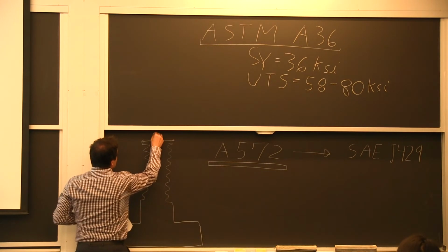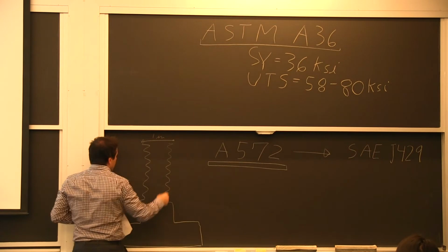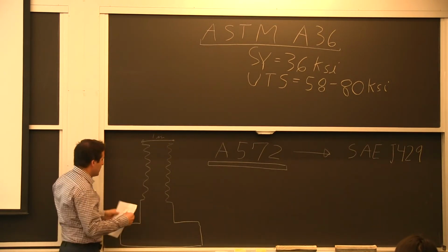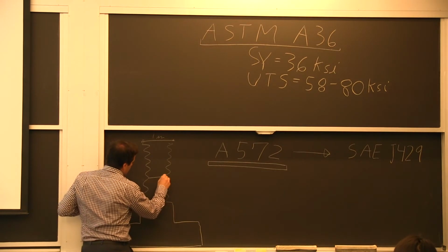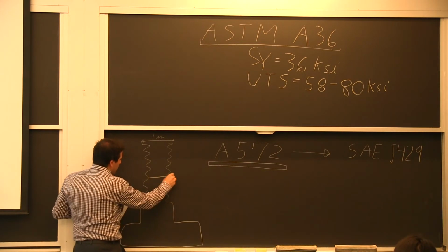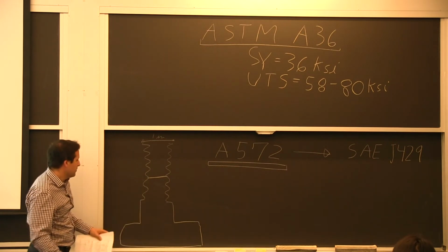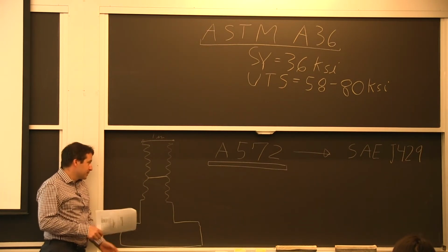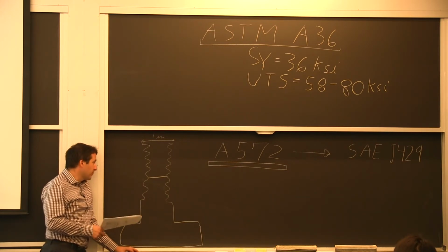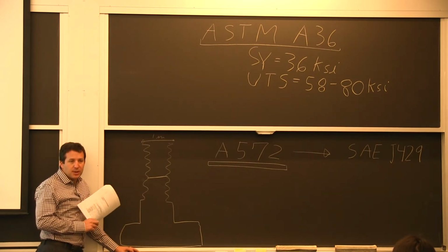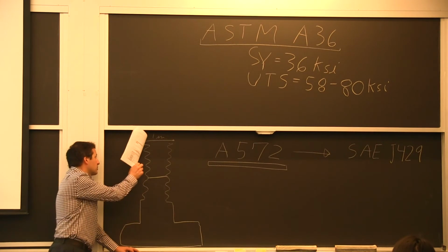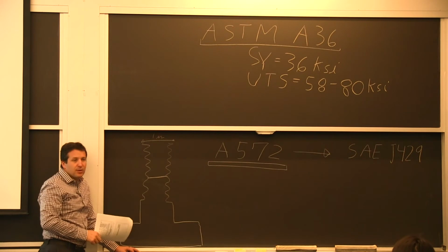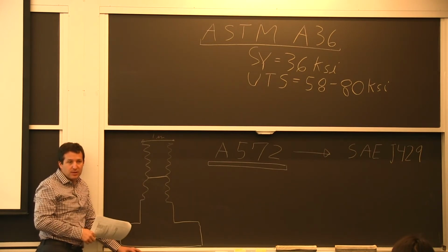If I start with a nominal 1 inch, it gives me a certain nominal stress through here, and then I have what we call a net stress here when I consider just going all around the root of the threads. That's already a knockdown factor of 30% sometimes. So that's the difference between the gross or nominal stress level and the net or effective tensile stress level.